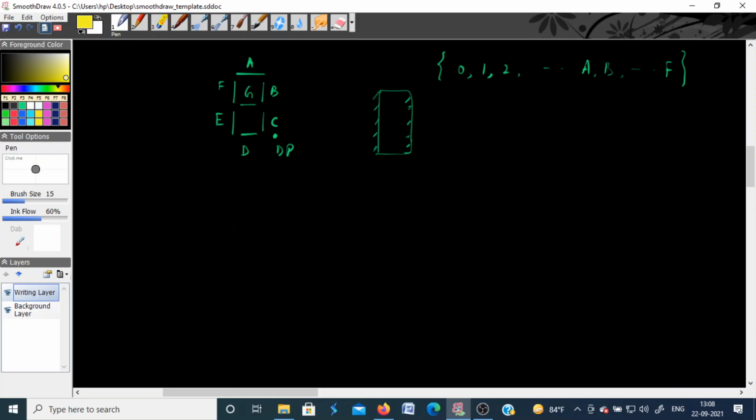And how the diodes are connected physically, basically in the common anode configuration. So all the P terminals are connected together, in common anode configuration. So you have one LED, 2, 3, 4, 5, 6, and 7. All these 7 LEDs, their P types or anodes, are tied together, and it is basically connected to the power supply, that is plus VCC.